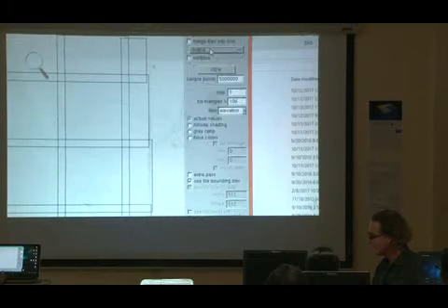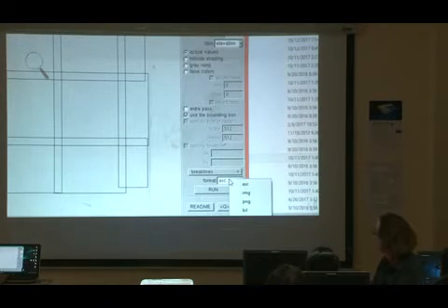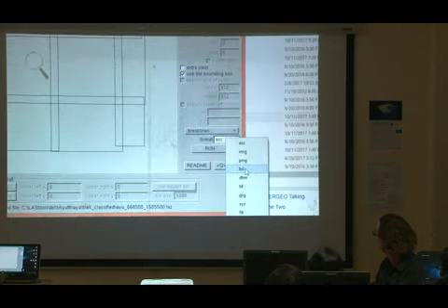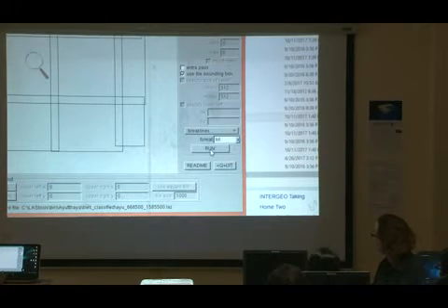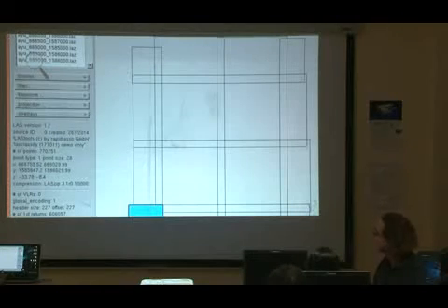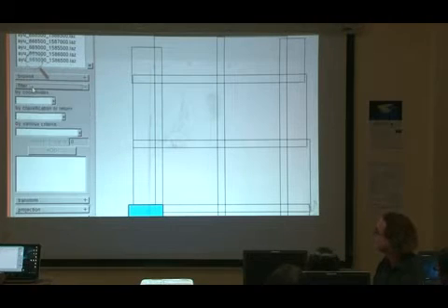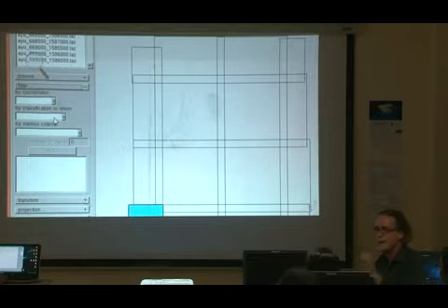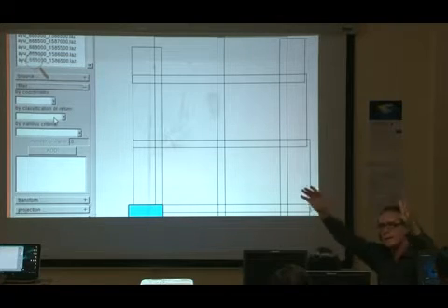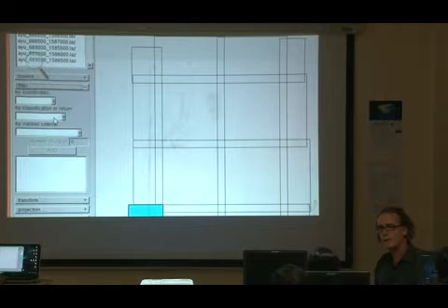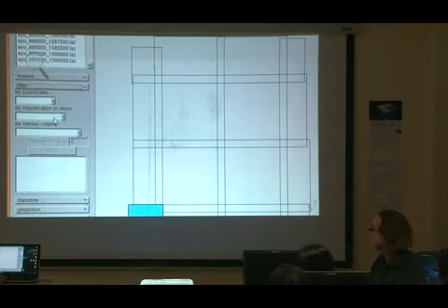And as my output format, I like to use the build format. It's more efficient than the ASC format. And one more thing, almost forgot, I need to filter. Now I don't filter on the buffer points, because I want the buffer points, I'm creating the tin with the buffer points. The cookie cutting comes later, when I create only a raster in the center of the tile.